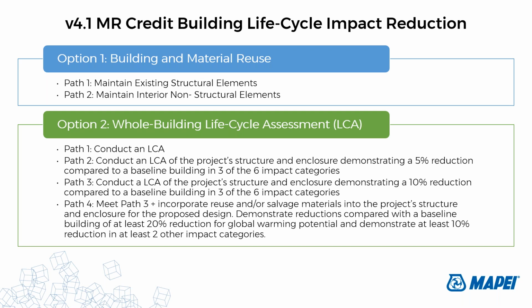And some of these impact categories are global warming potential or depletion of stratospheric ozone layer, and I'll talk about those more in a little bit. Manufacturers do not complete this LCA. Sorry, LCA stands for life cycle assessment. I apologize if I don't spell out what acronyms stand for. But the project team uses all available EPDs from all materials or products on the project site to complete a whole building LCA. And there's a special life cycle assessment calculator to complete this credit.